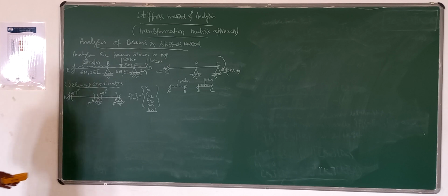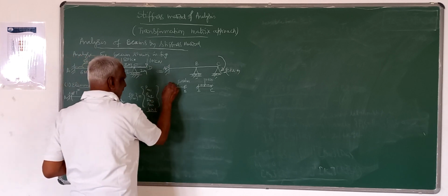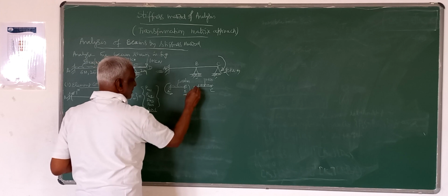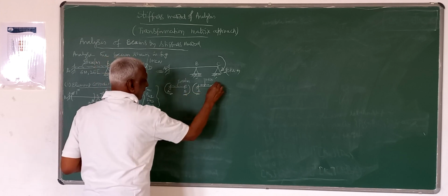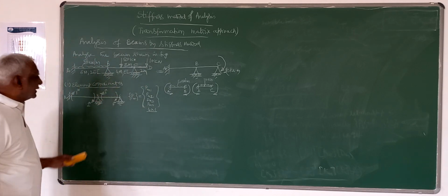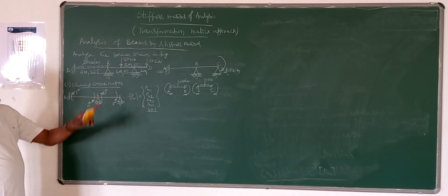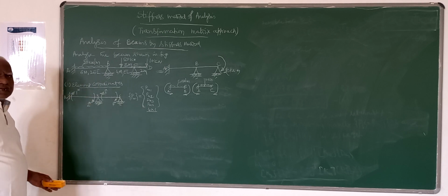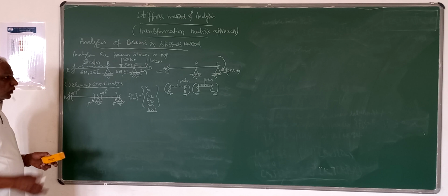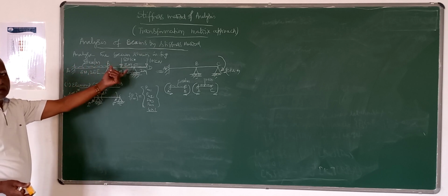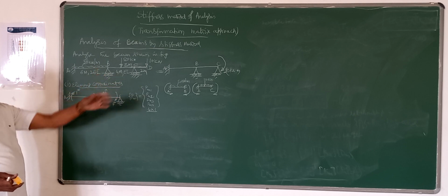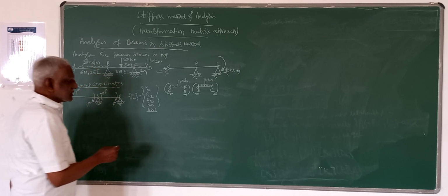So we assume the members AB and BC to be fixed, and due to that fixity, we find what fixed end moment develops, and those fixed end moments corresponding to these element coordinates we take for the analysis purpose as the external load. Instead of the member load acting on the structure, we convert that member load into equivalent joint loads.